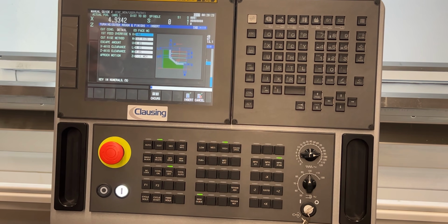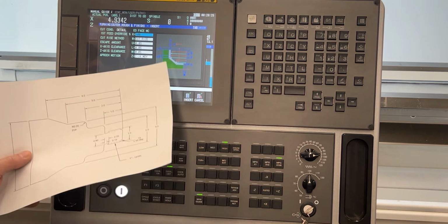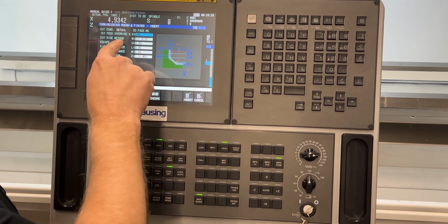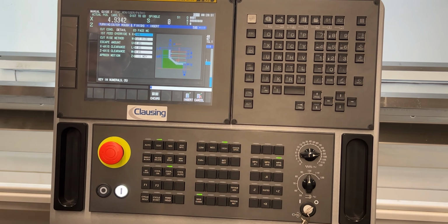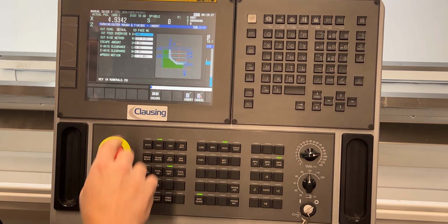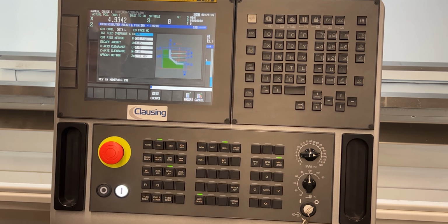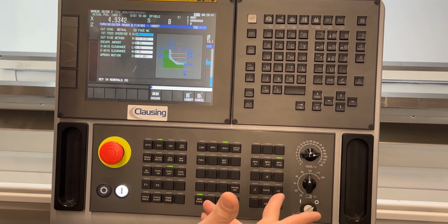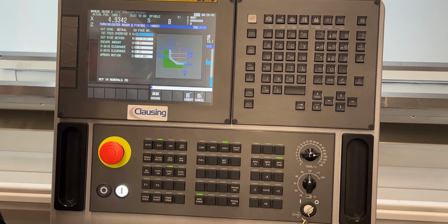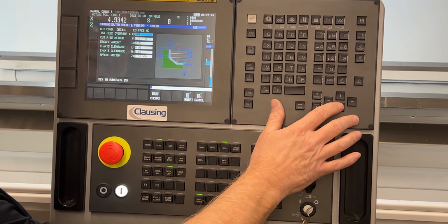The next screen has another enhancement from Fanuc Control, and that's my first speed override. So right now it's at 100%, so my first speed rate will be at 12. If I put that at 50, then my first speed will be at 6 thousandths per rev. Once it makes that first pass, then it'll revert back to the 12 thousandths per rev. I'm going to leave that at 100%.